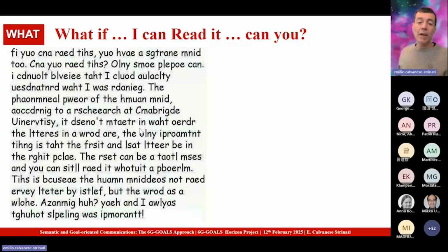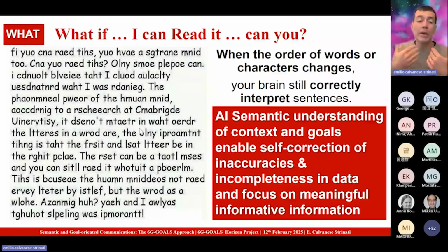And what we are using here is to relax some constraints at the physical layer, because we can accept a level of noise. We show that, for example, we can reduce the surface of the antenna we use for transmission. We can also reduce the signal to noise ratio we need for transmission, and so on. So we can have a not so good signal received, but still, with this additional level of correction from the semantic part, we are able to correct that.